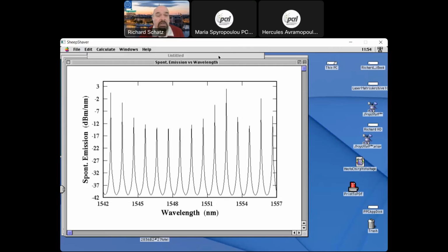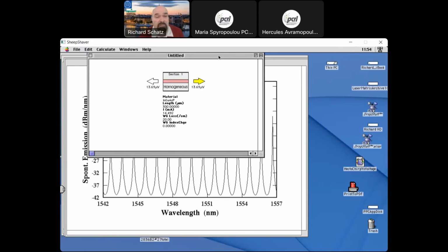All wavelengths where the cavity is an integer number of half wavelengths long, it will lase because the phase condition will be fulfilled. And the amplitude condition is the same for all modes. So you have no mode selectivity at all, which makes the Fabry-Perot laser not possible to use for fiber optical communication, for instance, because different modes will travel with different speed in the fiber, and then you could not go a very long distance in an optical fiber.